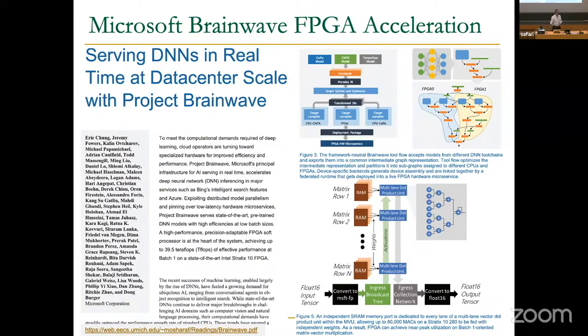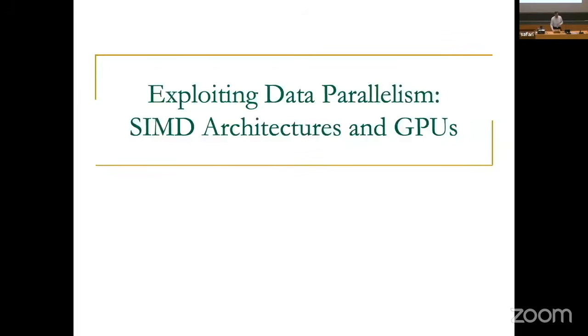But they do partly data flow mapping, directly accelerating part of the computation. But they also put soft SIMD units on the FPGA, just like you're doing in your labs right now. You're putting a soft processor, a MIPS processor, on the FPGA, right? You're not mapping, accelerating an application. You're basically implementing a processor on the FPGA substrate. They actually have a SIMD processor on the FPGA substrate also. At the end of this lecture, we may get back to it, even though we're not going to go into much detail because they don't go into much detail anyway.